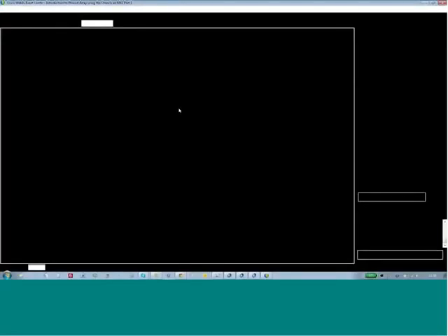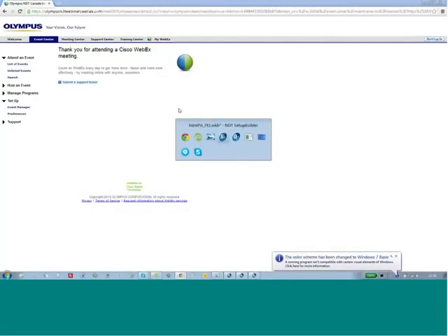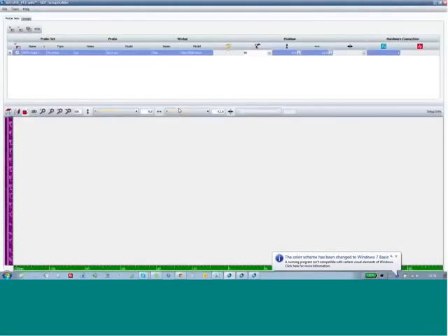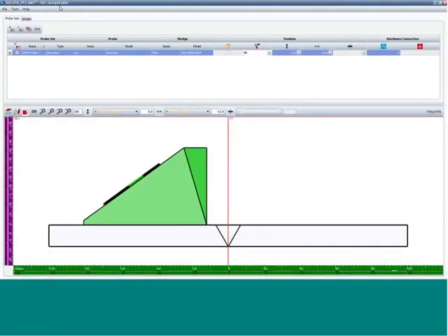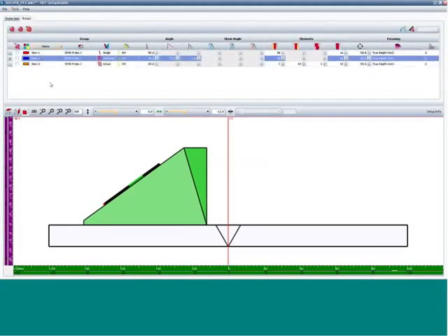Okay, so we're back in the NDT setup builder, which is what we use to plot. After we have configured the component, the probe, and the wedge, primarily from database entries, now we can move to the beam formation. A group defined in the OmniScan is a group of focal laws, or A-scans, that share a common skew and channel within the instrument.